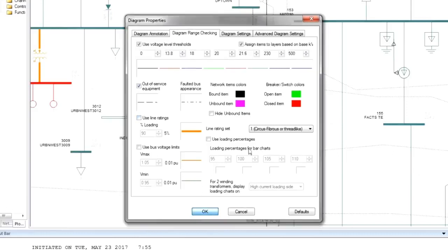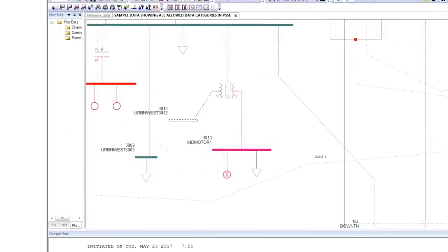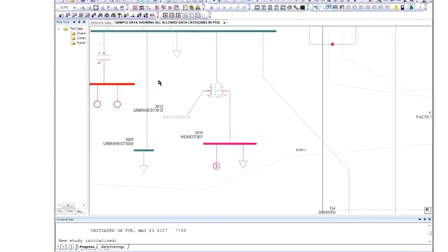Then click OK. Here you see transmission lines. In the center of the diagram is a 3-winding transformer. The transformer symbol also shows the grounding. There are machines, loads denoted by arrows, synchronous generators denoted by the circles, as well as 2-winding transformers and buses.